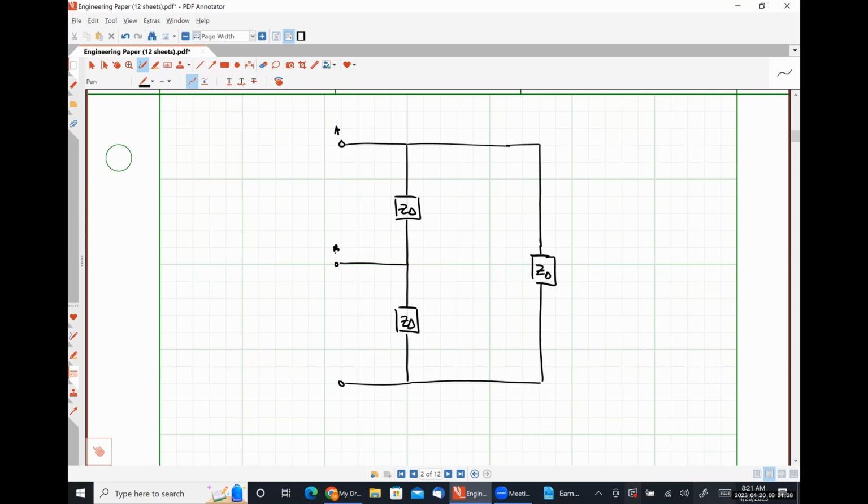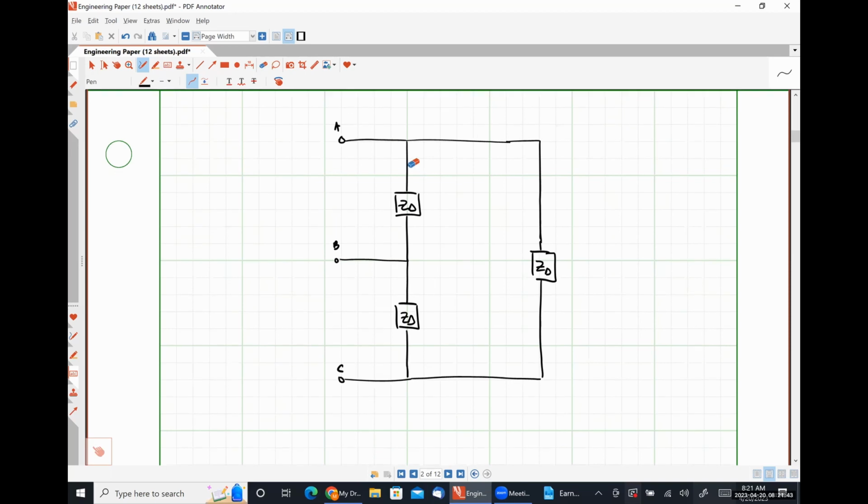A, B, and C. So if I were trying to connect 3 watt meters to this thing, and I'm trying to measure my phase current and my phase voltage, we're going to run into that same problem: we have to have an internal connection, because our phase current is inside the device, right?